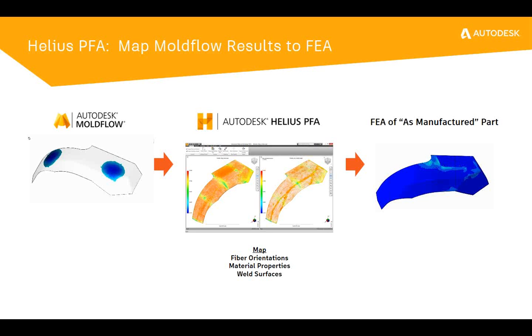Now, as plastics engineers, you know this is very important in that when we have high strain levels or high deflections in our plastic parts, the plastic or fiber reinforced plastic materials start to behave very nonlinear. And so being able to account for the nonlinear stress strain behavior in these plastic materials allows us to get the most accurate representation of our plastic part.